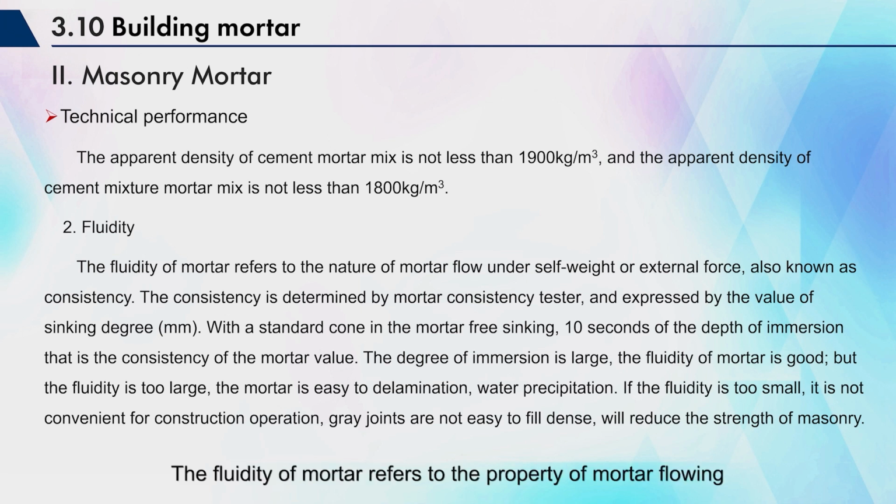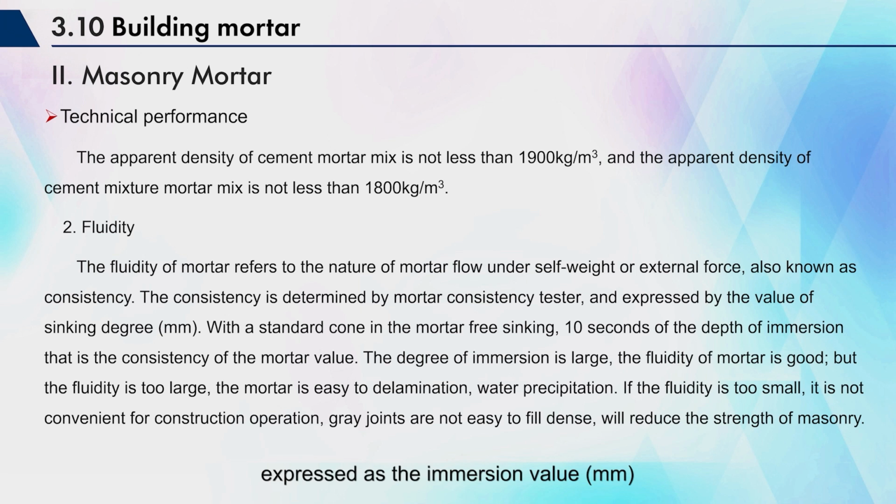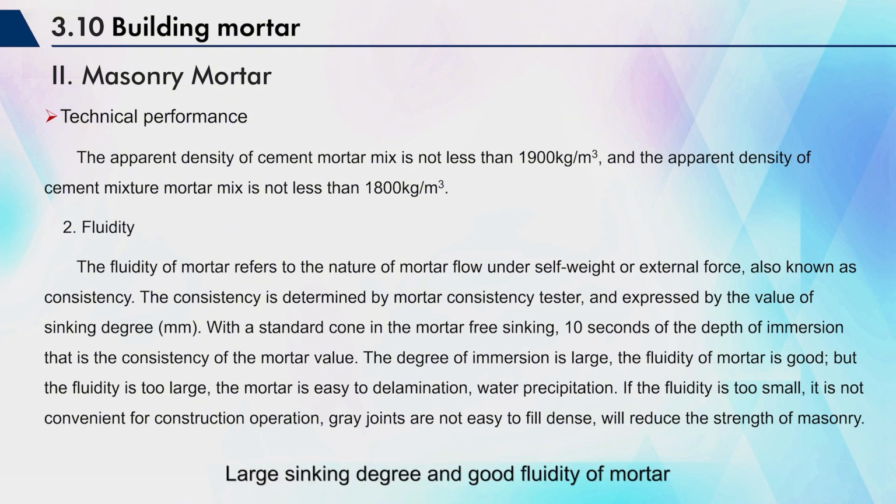The fluidity of mortar refers to the property of mortar flowing under its own weight or external force, also known as consistency. Measure the consistency of mortar using a mortar consistency tester, expressed as the immersion value. The standard cone is freely immersed in the mortar, and the immersion depth in 10 seconds is the consistency value of the mortar. Large sinking degree means good fluidity of mortar.